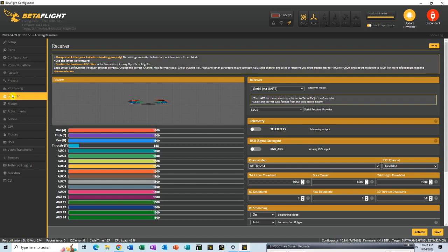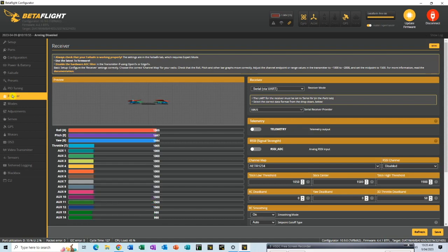And we're also going to switch on the receiver. So we've got everything functioning on here. Now, as soon as we get the signal back and everybody's green and happy with each other, because they should all be bound, right? We've got green on the receiver. Now, looking at the throttle on the receiver, if you push it, you want to get as close to 2000 as you can. 1996 for me is fine.